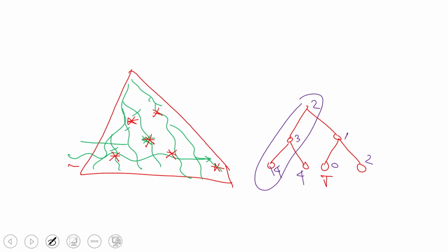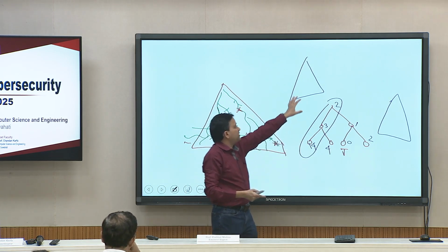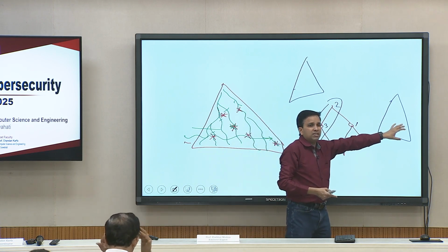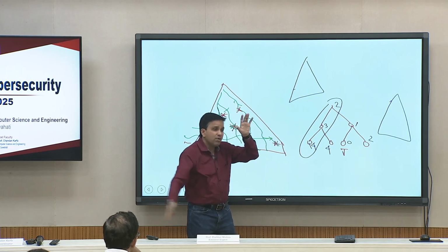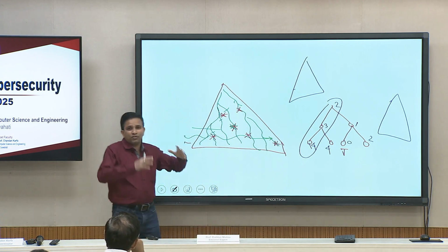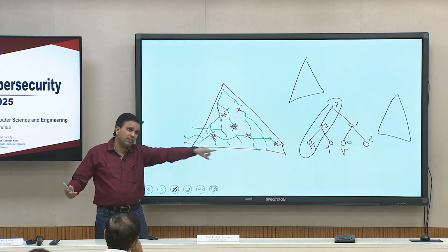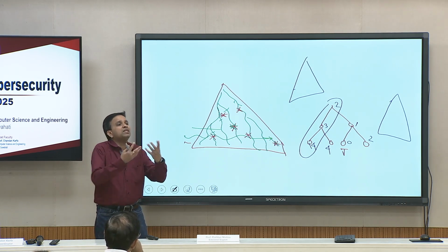But the reason that does not work, unless you unroll it: for the software domain it works like a charm, but in the hardware domain, you not only have this, you have another parallel one, maybe another parallel one. So, the global control flow graph is an intersection of all of them. Think of this as a state machine, this a state machine, this a state machine. It is basically the cross product of all the state machines you have to consider, and you have to unroll it for millions of cycles until the target becomes activated. If you try constructing that, then you will have the same problem as formal methods. So, that is why it has to be a lazy construction.